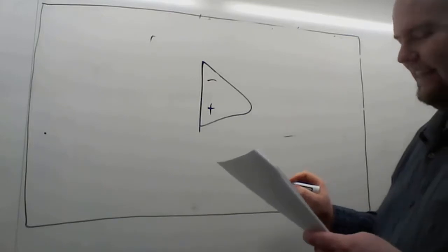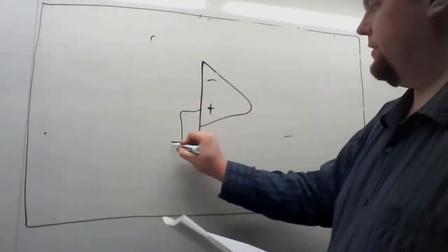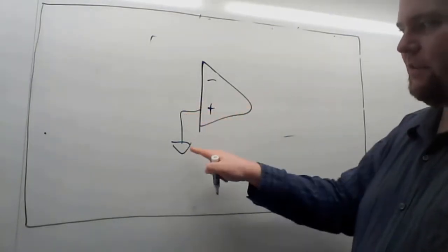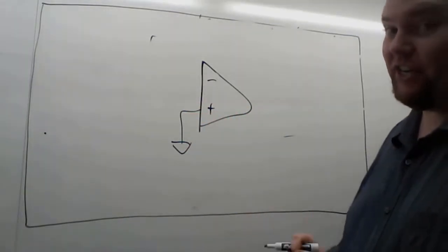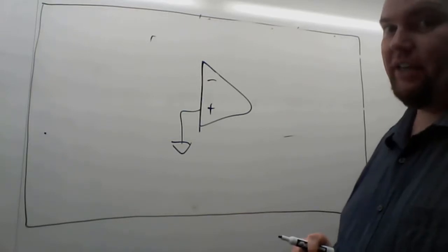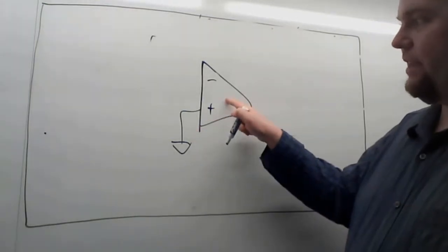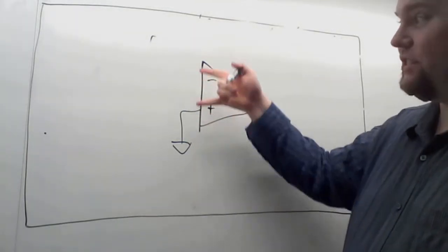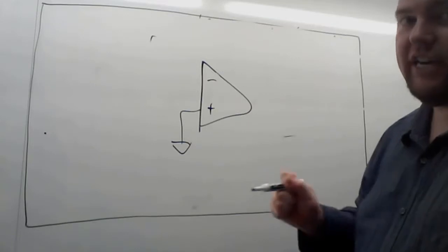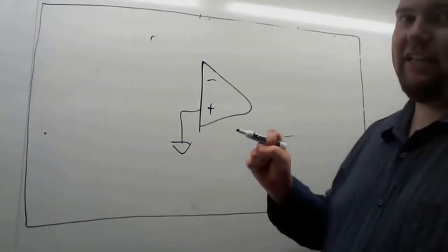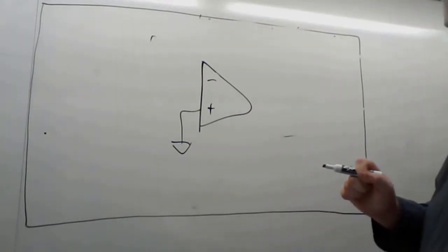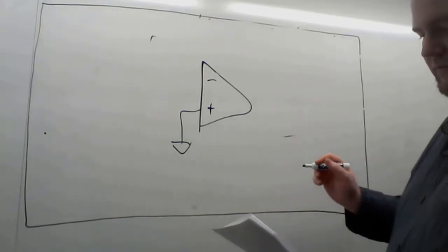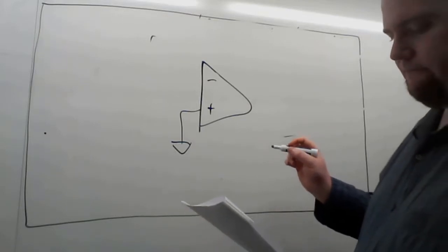I don't necessarily like that. Okay, so first of all, we should say when the positive terminal of my amplifier is pinned to ground, that's a good key that we actually have a current input. If one of the inputs is pinned to ground, that means the voltage of these should not be changing. It's a good indicator. Very likely, this is going to be a current input, which would be considered a shunt input. So that's just a good first test that that's probably the case.